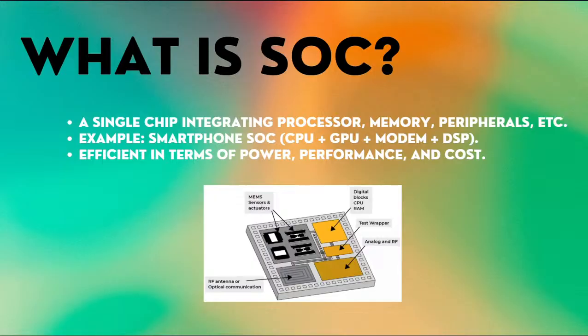For example, if you take any processor CPU core, like a microprocessor, it doesn't have any modem inside the chip. It doesn't have any RAM or GPU part inside the processor core. If you take any controller also, they didn't make CPU cores and GPU cores in the chip. But in the SoC chip, they made CPU cores, GPU cores, and then modem, internal RAM, and DSP block in a single chip. So that's why it's called SoC, system on chip. The whole thing is inside the single chip.